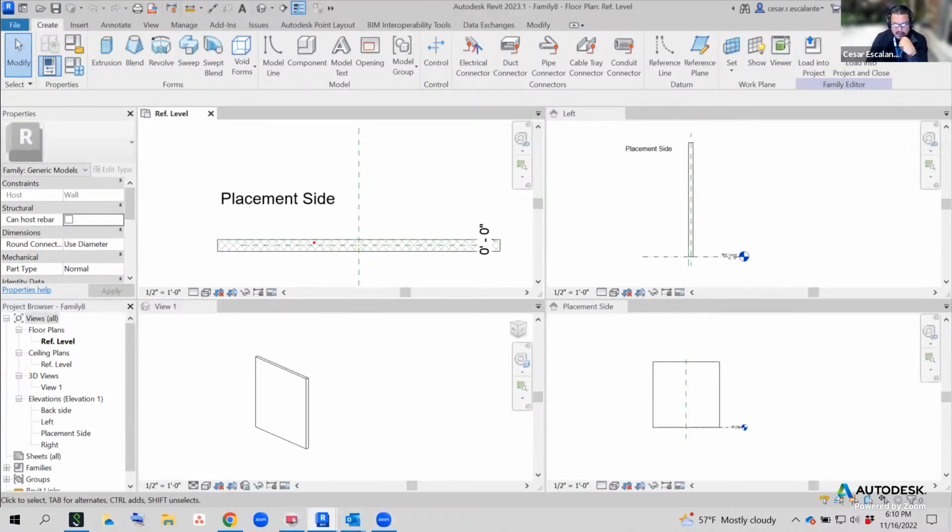This is a wall cabinet, and this wall that you see here is a generic representation of a wall. This wall is not going to transfer into the project. It's not going to be visible. It's in the template to represent what a wall looks like, and it's used there to help you create dimensional constraints that are locked or aligned to the face of the wall.